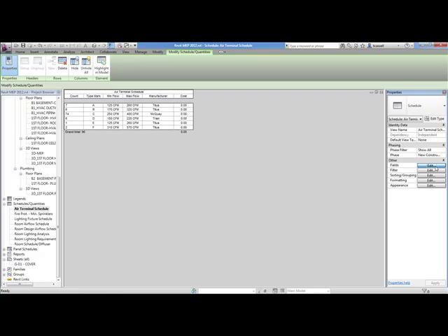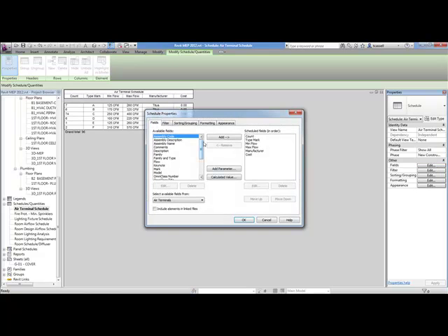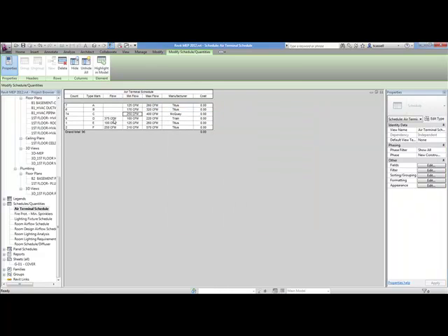I know what the minimum is, I know what the maximum is, but what's the average airflow for each of these diffusers? You get full control over doing things like adding assembly code, flow information, system abbreviation, system class, so I can tell if it's a supply diffuser or a return diffuser. So this would actually be called actual flow. So now I can look and say, here's the actual flow in all these diffusers. Here's the min and the max flow.